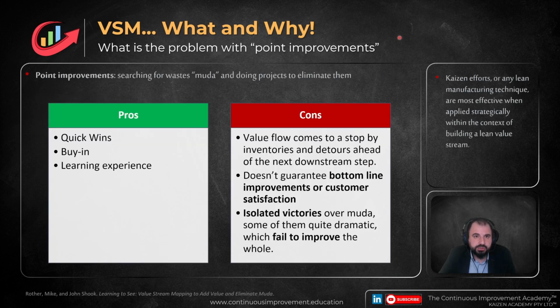If we focus solely on point improvement by concentrating our effort in one specific area of interest, we run the risk of missing out on numerous opportunities, or in some cases, even having a negative impact. For example, you may improve the productivity of a production step that's not a bottleneck and it's already faster and has a shorter cycle time than other processes.